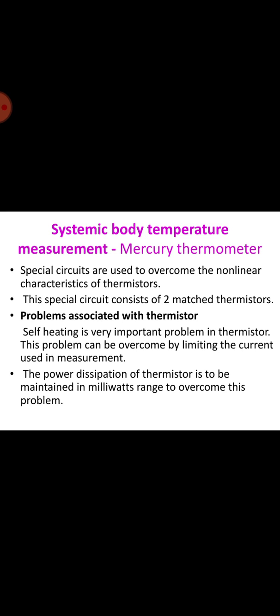The thermistors are available in several common configurations. The three most common configurations are the hermetically sealed flexible thermistor, the bolt washer type, and the self-adhesive surface mount type. Thermistors are highly accurate but only over a limited temperature range, that is within about 50 degrees Celsius of a base temperature. The working temperature range for most thermistors is between 0 degrees Celsius and 100 degrees Celsius.